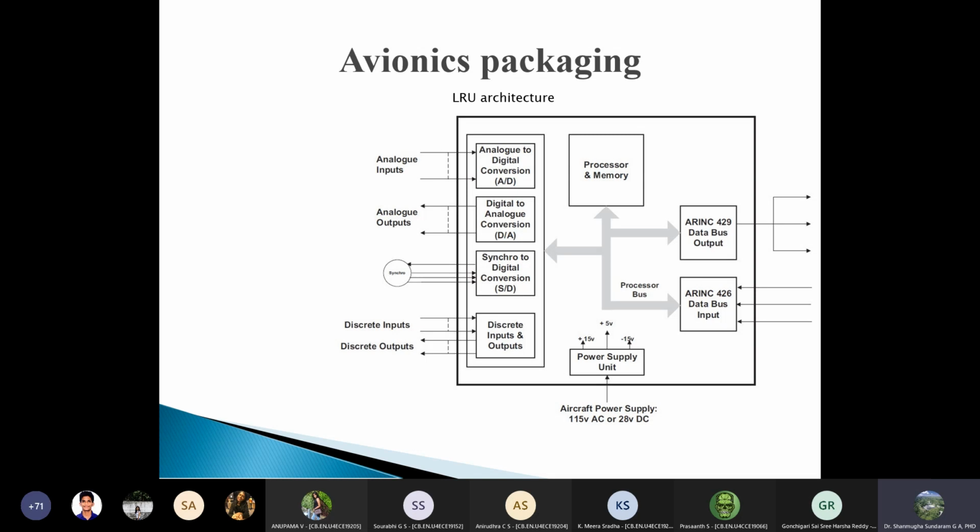The resolver is another name for the synchro. It is primarily a transducer that converts angular position and angular velocity, which is a change in angular position with time, of the rotating shaft into its corresponding electric signal. So if there is a change in angle of the rotating shaft of the engine as a function of time, that is broken down into a series of steps and encoded depending on the finer level of detail that one needs.